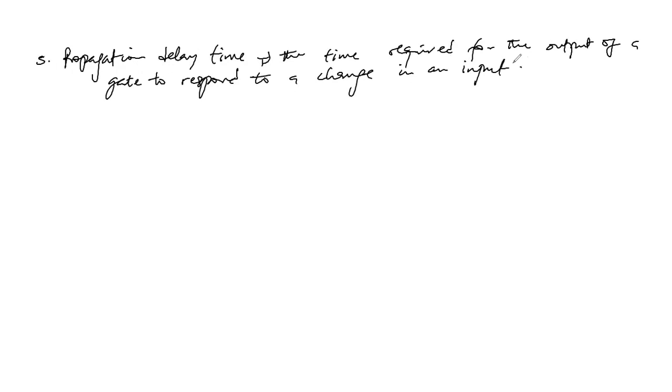In all practical gates, a time lag exists between an input change and the corresponding output response. So the time interval between the instant when the input and the output change states is not a satisfactory measure of the delay time of a logical device for two reasons.